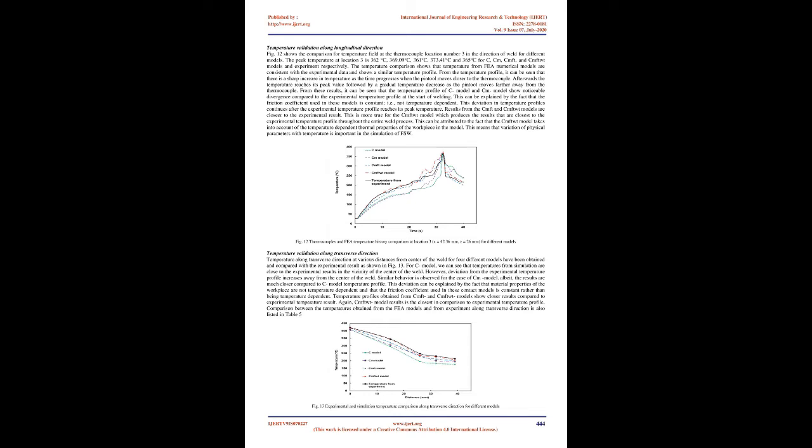CMFT model. In this model, the workpiece is also considered to be elastoplastic, and its material properties are temperature-independent. In the model, modified Coulomb friction has been used to model the pintool/workpiece contact conditions. The friction coefficient is considered to be temperature-dependent, see Table 3, in this case. CMFTWT model. In this case, the workpiece is considered to be elastoplastic, and the workpiece material properties are considered to be dependent upon temperature. In the model, modified Coulomb friction has been used to model the contact between pintool and workpiece. Also, the friction coefficient has been assumed to be temperature-dependent, as seen in Table 3.